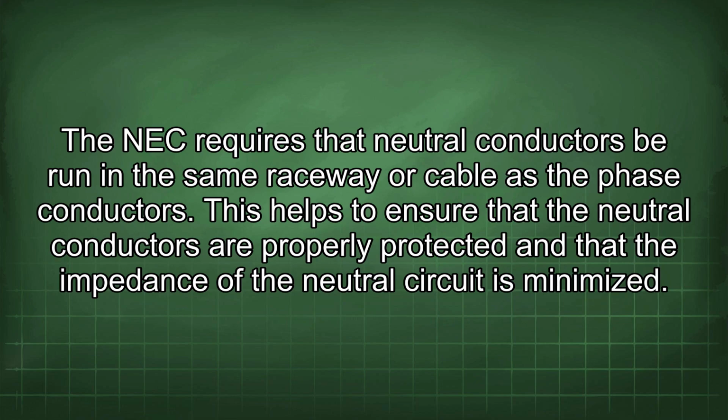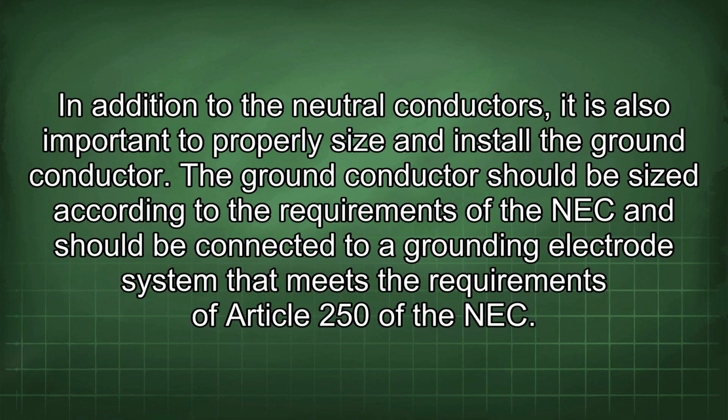The NEC requires that neutral conductors be run in the same raceway or cable as the phase conductors. This helps to ensure that the neutral conductors are properly protected and that the impedance of the neutral circuit is minimized. In addition to the neutral conductors, it is also important to properly size and install the ground conductor. The ground conductor should be sized according to the requirements of the NEC and should be connected to a grounding electrode system that meets the requirements of Article 250 of the NEC.